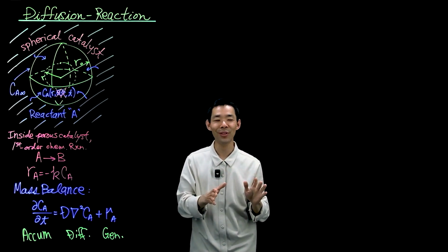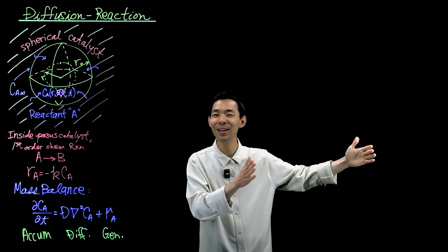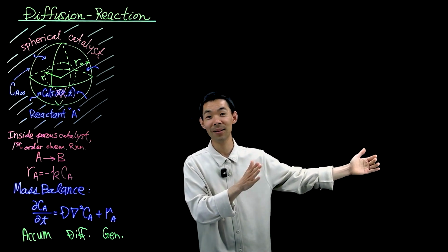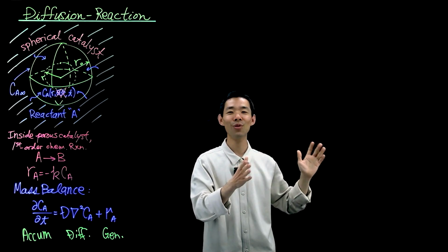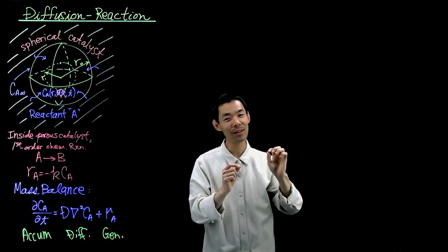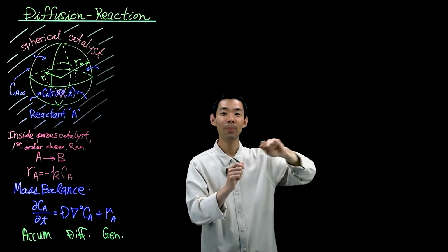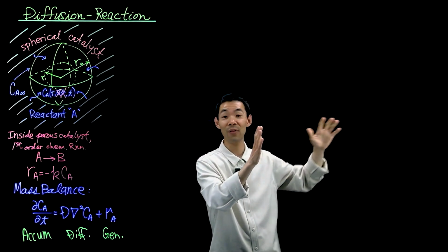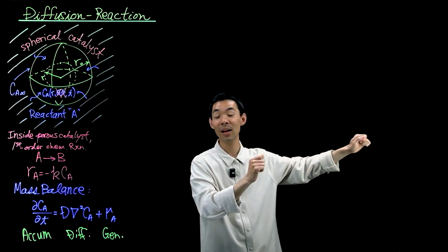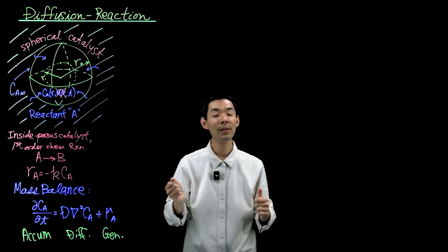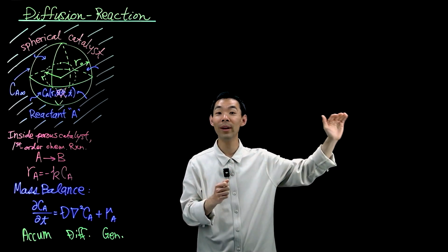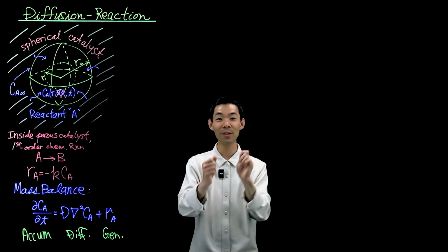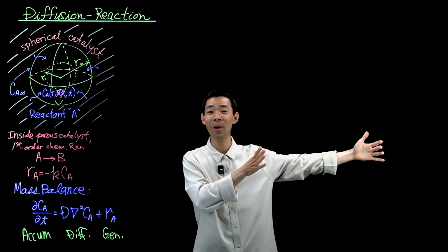But in most applications, your reactor is running continuously for a very, very long time. In effect, it's running at steady state. You put your reactor, this huge tank, there's an initial transient, and there is an importance of how to do that transient carefully, but the ideal case is the transient would die away, and you'd run it at steady state at a fixed situation for a very, very long time to maximize your output. So let's first consider the case where you're running all the way at steady state, where the transients have died away, and you only care about the steady state operation. Because as an engineer, you want to ultimately maximize steady state profit.